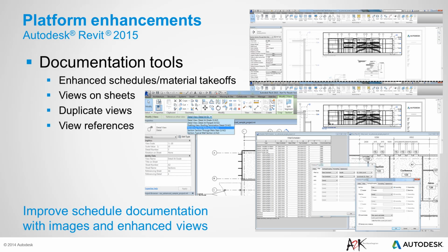When using view references, you can now change the referenced view after the view reference has been created. You can change the view reference in the reference callouts, reference sections, and reference elevations after the reference has been created.